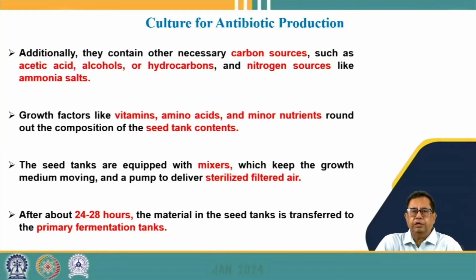Similarly, the growth factors, for example, the vitamins, the amino acids, the minor nutrients, all have to be added into the seed tank, so that the growth of these microbes can be enhanced. And these seed tanks may also be equipped with mixers, so that the contents of the seed tanks may be moving and mixed properly, and a pump is also used so that we can deliver the sterilized filtered air, if it is required in such a process.